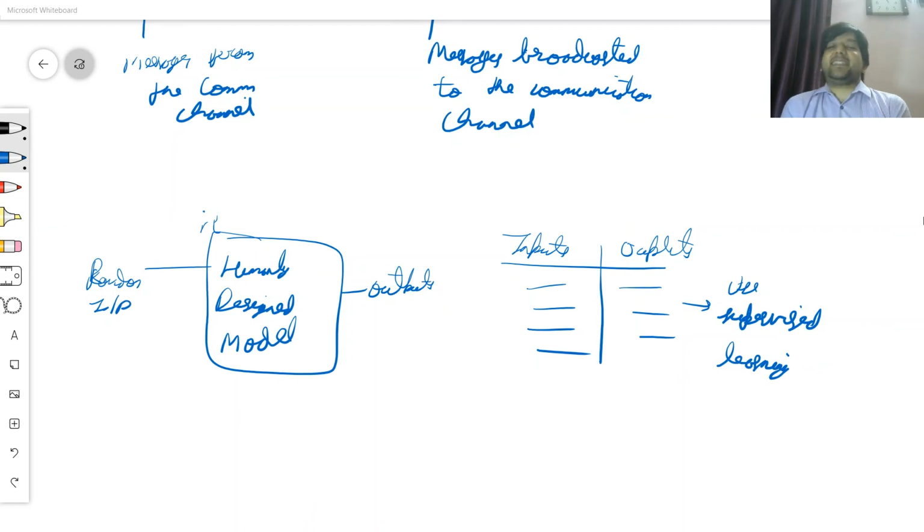The best is to go completely autonomous, use something like a potential field, A-star, potential field navigation, velocity obstacle. So these are established algorithms. They make the robot do interesting things. They can be tuned up for interesting behavior. So you get a lot of data for free. The algorithms run day and night, and they make a robot move, and you are just logging and making a machine learning system learn the model. So your recurrent neural networks, your LSTMs, are learning autonomously on this data.